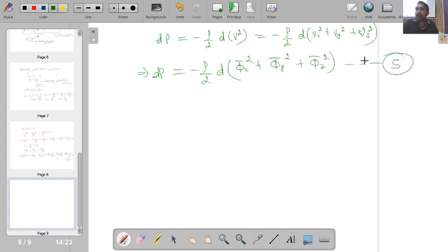Now another important point is, we know that del p by del rho for an isentropic flow situation is nothing but equal to a square. Whenever we study irrotational flow, from Crocco's theorem also you can see, for irrotational flow our entropy gradient will be equal to 0. So irrotational flows are nothing but of isentropic nature.